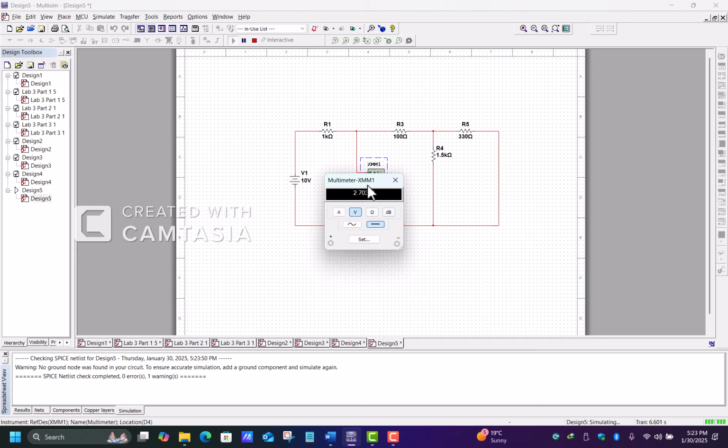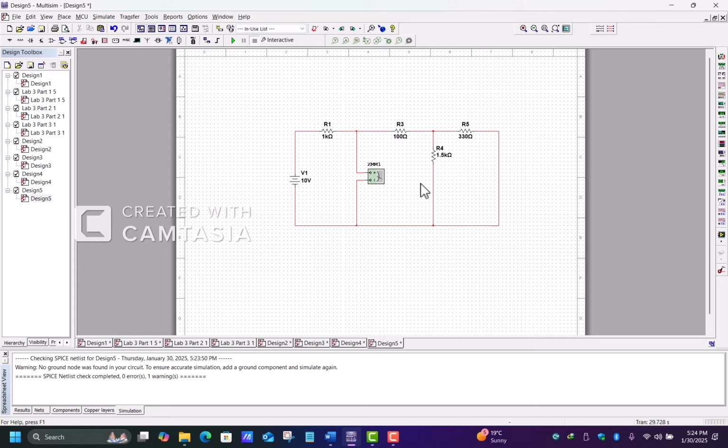So this is my voltage drop. This is the Thevenin voltage one in terms of the 10 volt voltage source, the first voltage source. This is for the first voltage source. And we are short circuiting the second voltage source of the circuit, applying superposition theorem with Thevenin circuit.